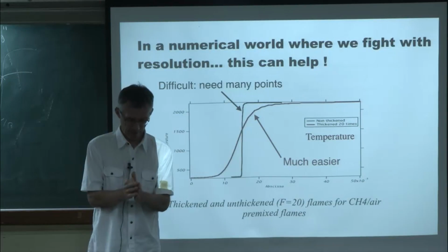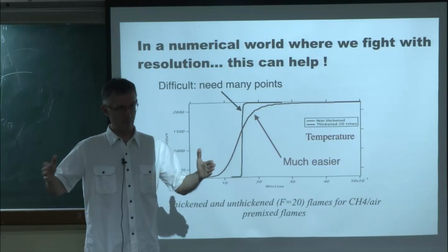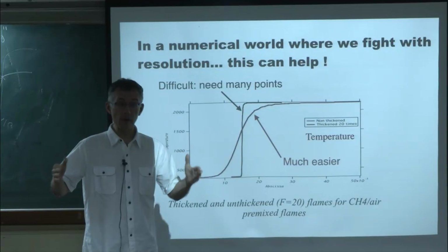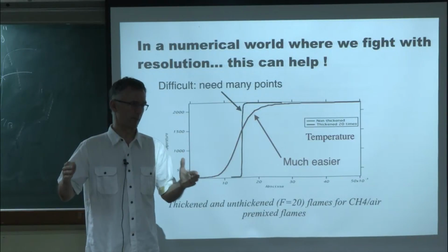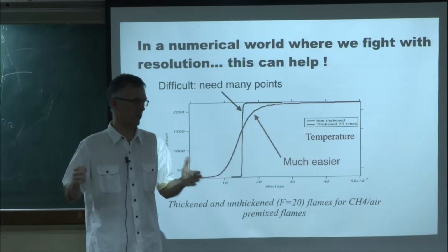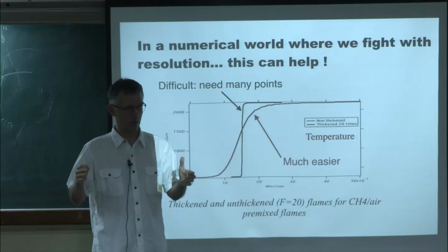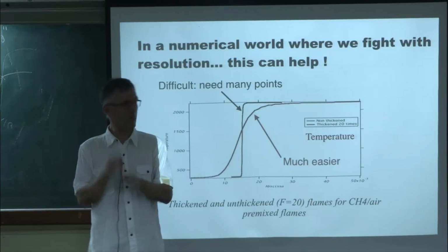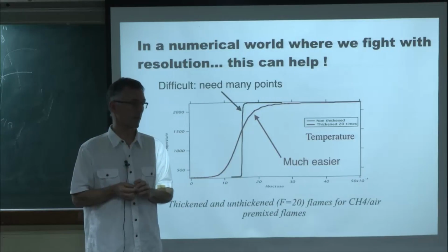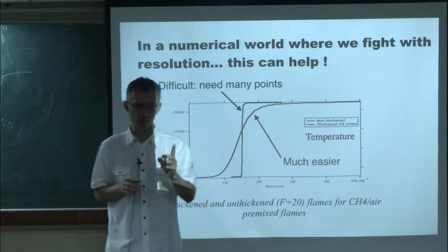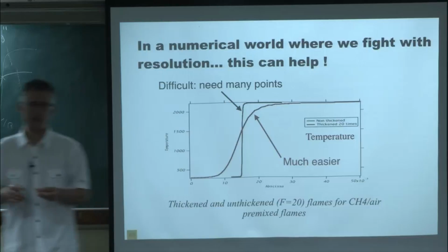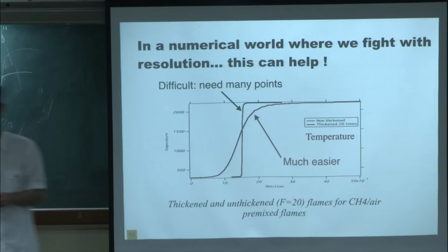When the flame is very thin, or if it gets very large, it does not respond to the flow in the same way. It does not respond to stretch and to curvature in the same way, so we'll have to do corrections. But for the 1D laminar premixed flame, it's exactly the same. Okay? But when we go to the turbulent case, there will be a price to pay. I mean, there is no free lunch, okay? We need to compensate. We'll do that this afternoon.